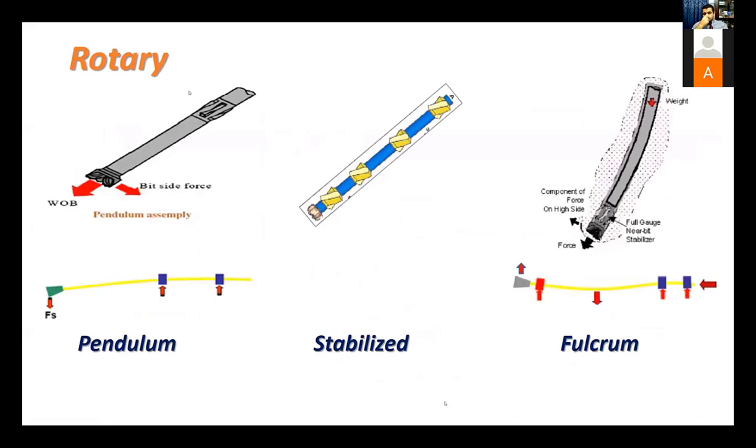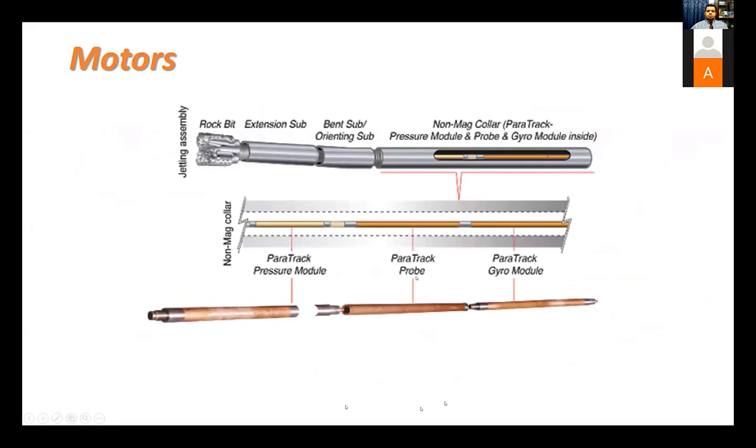You can either do it with a rotary technique using the pendulum, stabilized, or fulcrum principles using stabilizers, or you go for the motors, mud motors in specific. And after that, you can see the rotary steerable set.